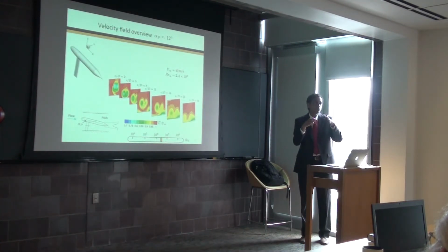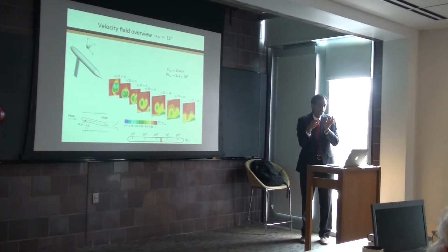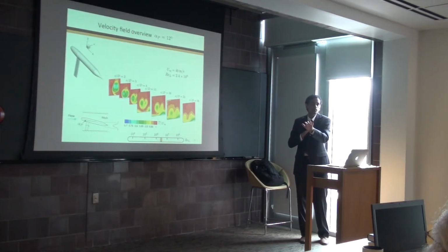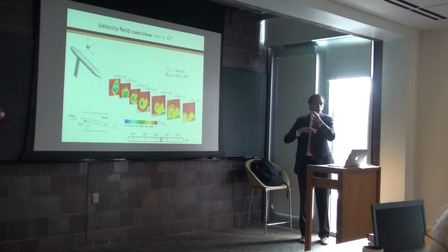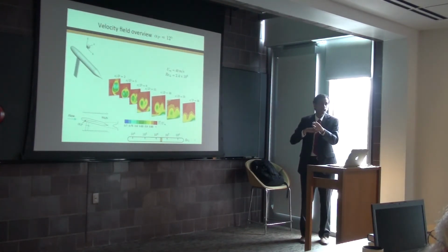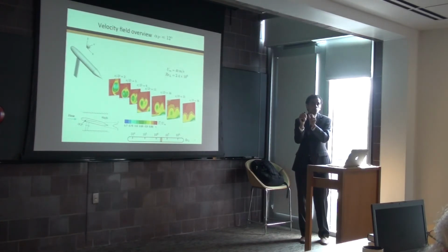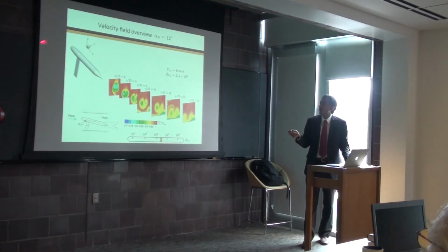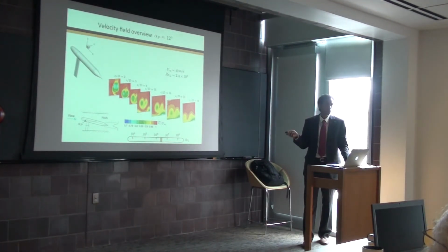And there you see this asymmetry is a well-accepted way of controlling more than living with it. You control the flow with that because your rudders and your control surfaces don't get clean separated flow. So they're not very helpful to you when you're an F-16 pilot at 45 degrees angle of attack. What you can do is use the asymmetric bursting of these vortices, basically vortex bursting that's occurring, as a way to control your flow. There have been workers that have suggested this, but at low angles with blunt noses. So what I do is low angles, blunt noses.